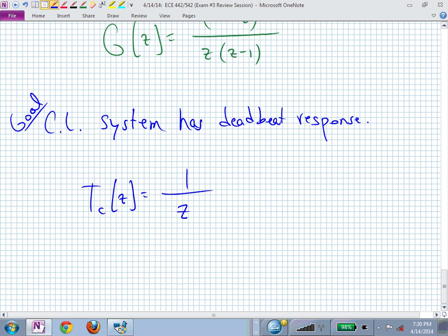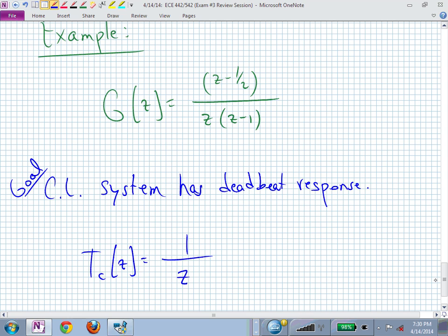Now, restriction 2 in play? No, we don't have any unstable zeros, do we, in our original system? How about restriction 3? Here we don't consider z equal to 1 unstable. That's okay. We're going to force our closed loop pole to be right at the origin. So we don't have to worry about preserving that pole at z equal 1. We're going to move it in.